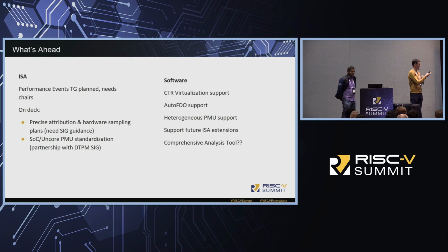We're also looking at PMUs outside of the CPU, what I call an SoC PMU, or some call an uncore PMU. So PMUs in your IOMMU, in your memory controller, et cetera. Can we look at some standardization and discovery mechanisms there? I think we'd be kind of an industry leader if we can get that done.